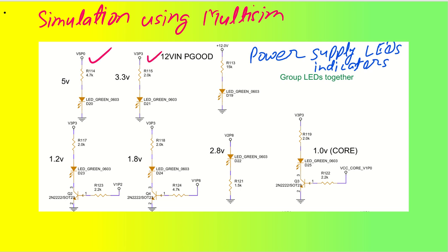So you would have seen that this is my 5 volt indicator, like 5 volt I have supplied here with one resistance, and this is my LED. This is the circuit design that we have done in our system circuits. We want to simulate this so that we can see whether the LED is glowing or not. Similar to that, we have a 3.3 volt indicator, we have a 12 volt indicator, right? So for 12 volt, you can see the resistance is increased so that the current can be limited.